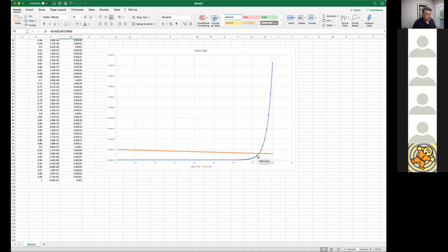And we're doing the same thing when we're doing the numeric estimation: we come up with a starting point. We wouldn't come up with a starting point of 0.3 for VBE, because we know that's not a reasonable value. You can just see it from the graph, right?